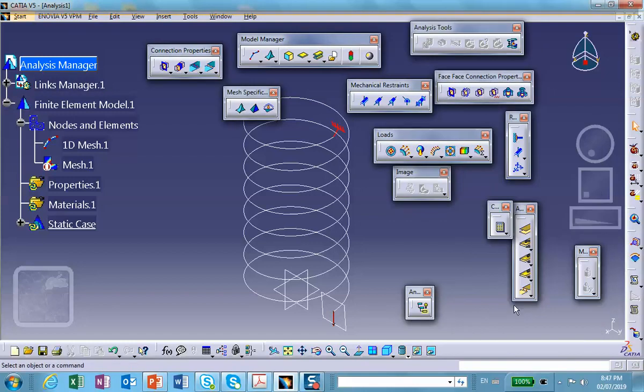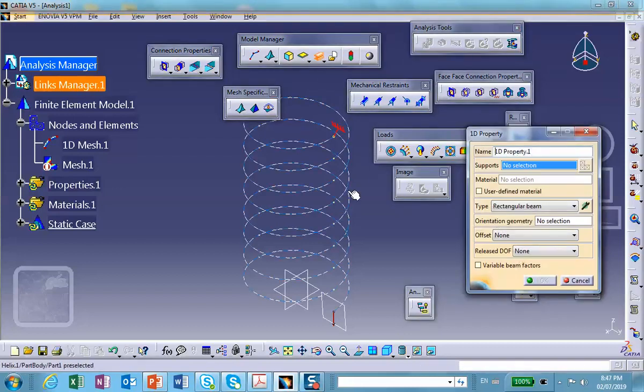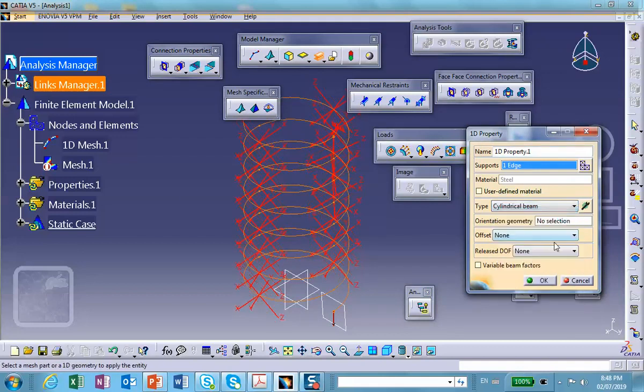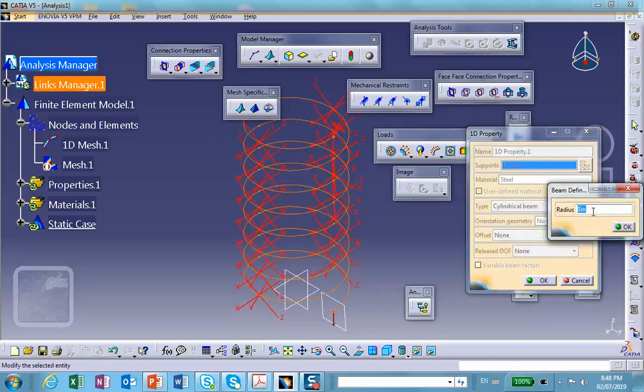Now I have to tell the software what the shape of the cross section is. Obviously, it's a circle. So you go to the model manager where the traffic light is. Click on the 1D property. Select the coil, and the cross section is not rectangular, it's a cylindrical one, and the radius is not 0. Obviously, let's make it 0.25. That looks like...